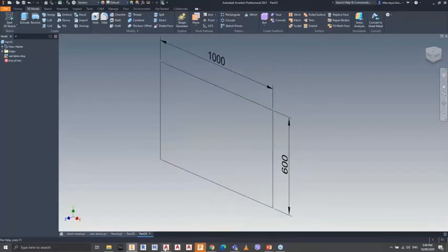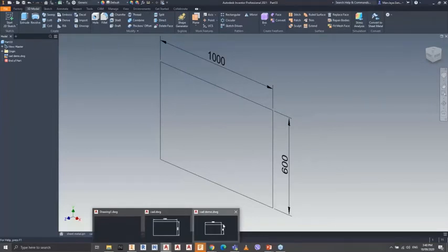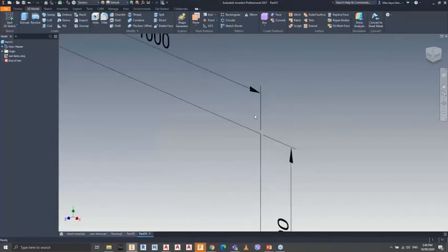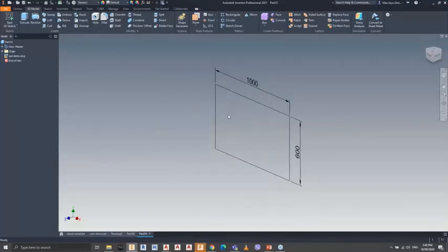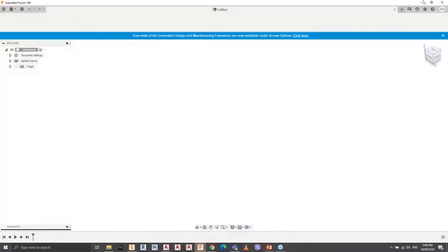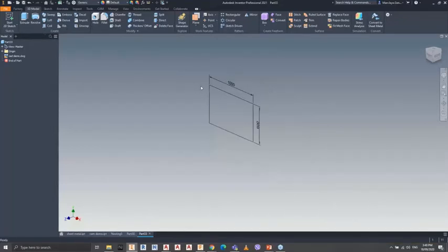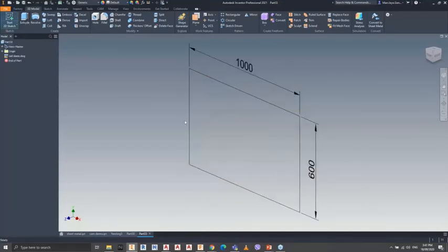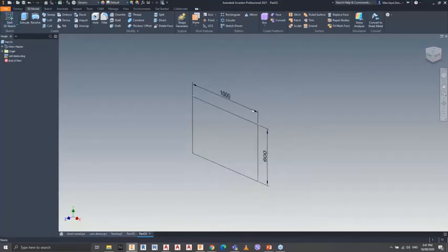Okay, so this is the data coming from our AutoCAD file, as you can see here. So what we are going to do next, if you're going to improve the model and apply the extrusion, for those who don't know yet about the extrusion, this is our way on how to put height or thickness on each object. Unfortunately, using this link file in our Inventor, you cannot directly create an extrusion for that, because first, you need to convert the 2D from AutoCAD into an Inventor sketch model.